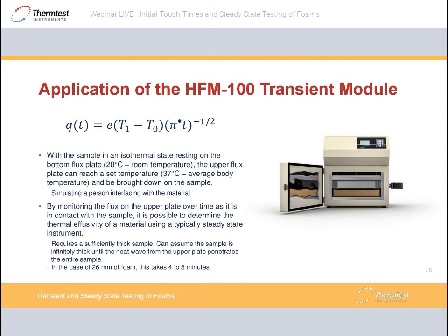By monitoring the flux on the upper plate over time as it is in contact with the sample, we can determine the thermal effusivity of the material using this instrument that's typically used for steady state methods.